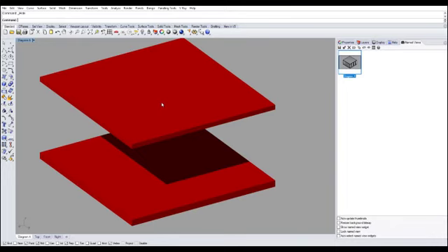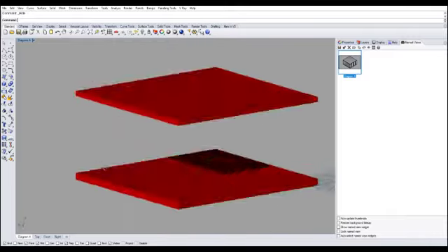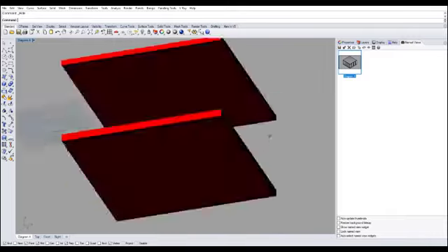Anytime you want to return to where you were before because you made a mistake, you clicked on the wrong thing, just simply press Control Z. Rhino pretty much remembers every step and everything that you've done up until that keystroke. So there you have it. We only have our roof and ceiling open. Now this is ready to render.